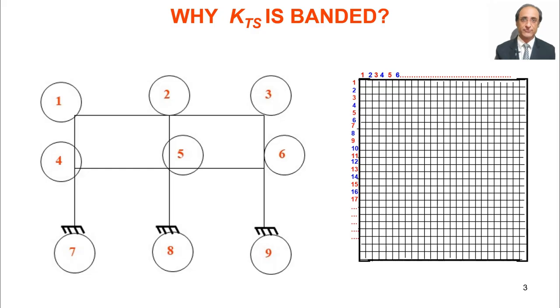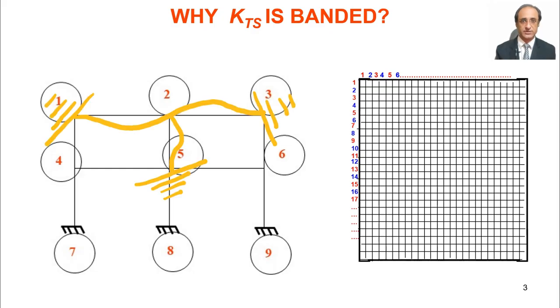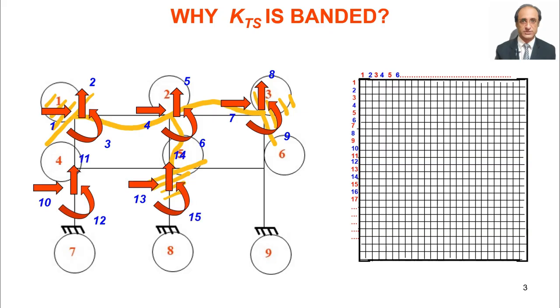So let's do this process that we have here degrees of freedom 4, 5, 6 at joint number 2. So let's say we apply a unit rotation here and lock all other degrees of freedom. So we have applied this, what we have enforced, and now the forces generated along various degrees of freedom, they will be the 6th column of the stiffness matrix. Now you see the values.